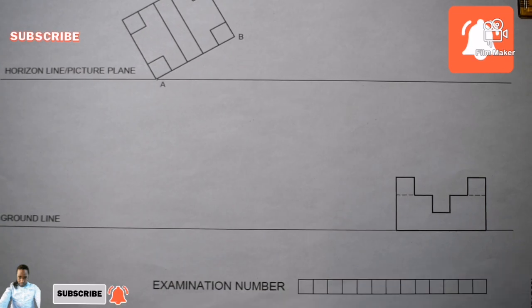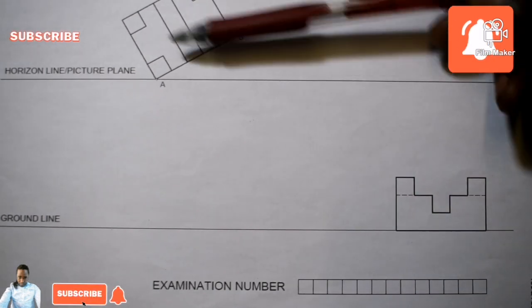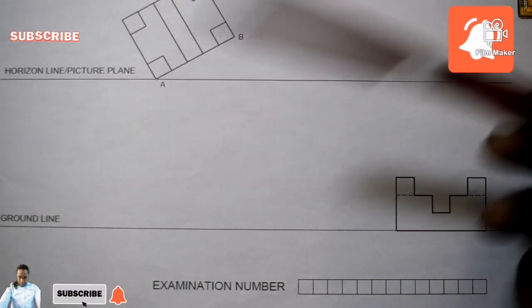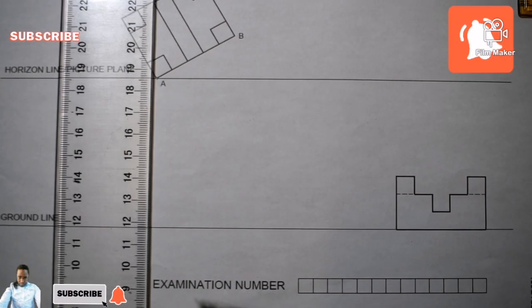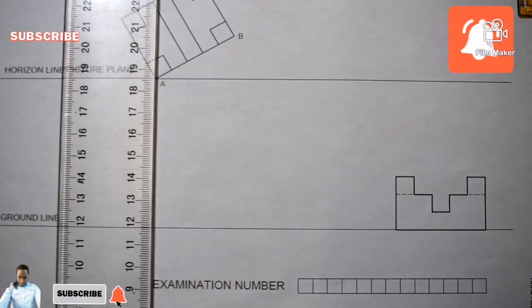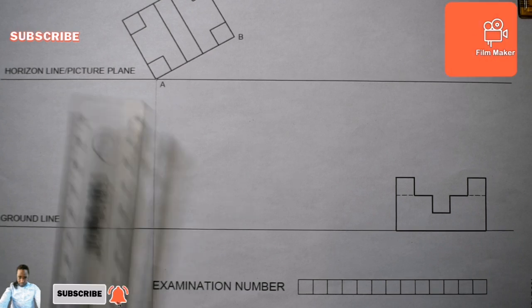As far as I'm concerned, this is what is given to us, isn't it? I think they zoom in and out. The top view is actually a little bit skewed, but we are going to use it just the way we are given. So I'm going to have a faint constructional line that's going to go horizontal, vertical, going down. So from here going down, I'm going to record that dimension of 100 millimeter.